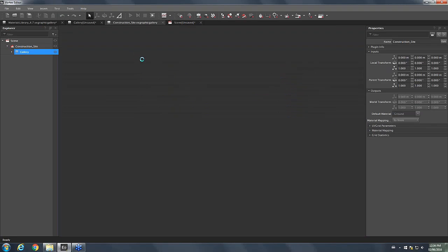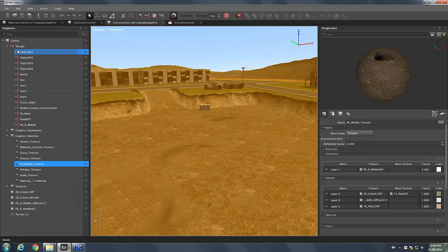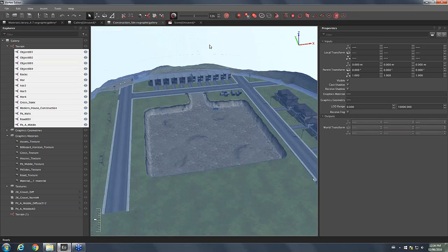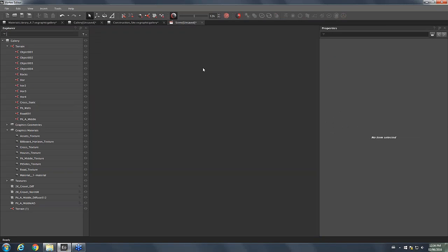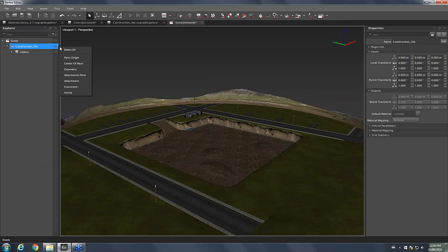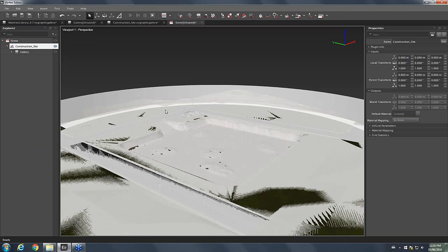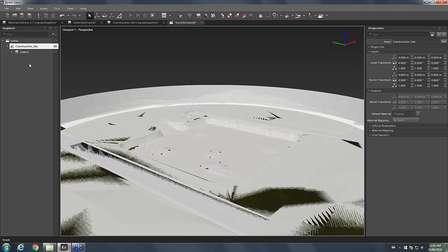So if we open the graphic gallery, it's possible to modify it like this. For example, if we select just the houses and we don't need them, I can remove them in the graphic gallery, go back to my scene, and they're gone from the terrain. And if we check the collision geometry, the houses are gone indeed. And so that way you can use the gallery to modify terrain according to your need. Back to you, GP.